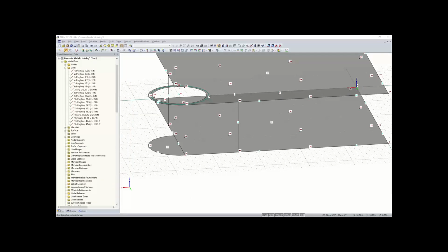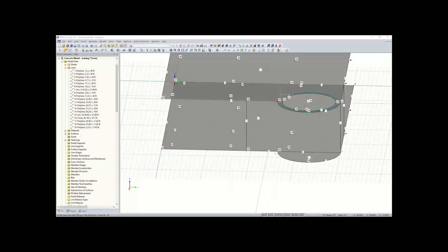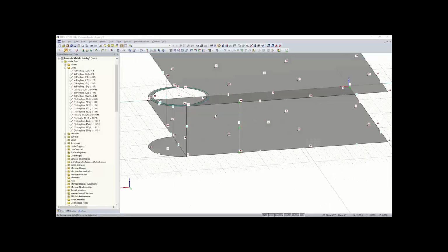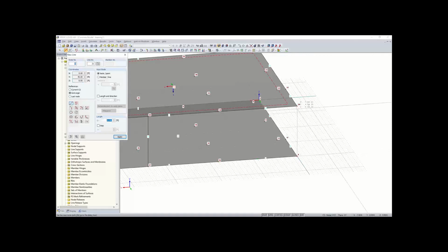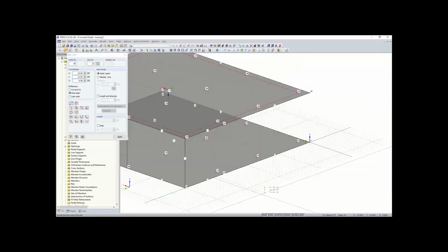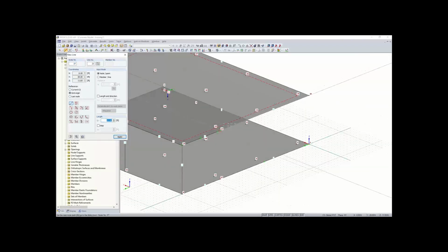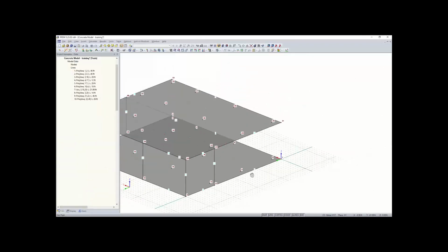And now we can simply just connect the rest of our nodes here, we don't have to create any more nodes. We can just connect 3 and 23. Let's see, 20 and 40. What else? 4 and 24. Oops. Looks like I created a line there. Control Z. I can go back up to new line and just connect 4 and 24. And then we also want to connect 18 and 38. And also 17 and 37 here. And again, these are just creating our boundaries for our walls.